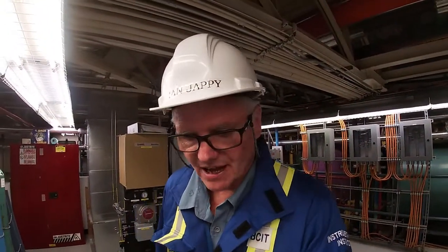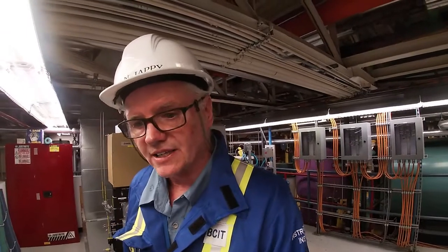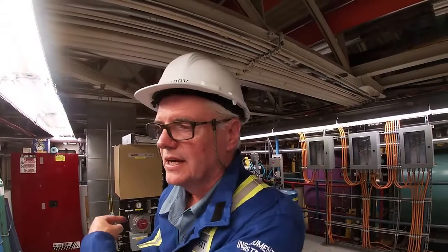Now you can see the valve shut. That's part of the safety system. And if we were to check downstairs the motor, you would see the motor has stopped in the MCC. There's a contact in there, and we can go down and have a look at that. There's a contact in the motor circuit that comes from the SIS system. That needs to be closed in order to energize our start-stop on our motor. So as soon as we had the 2 out of 2 voting, we tripped, that contact opened up in the starter, and we shut down the pump as well.